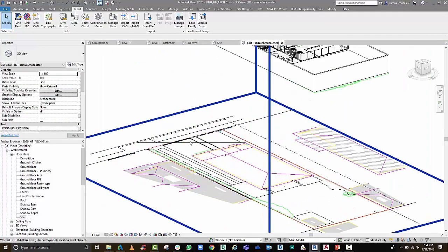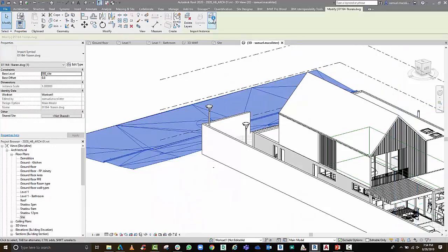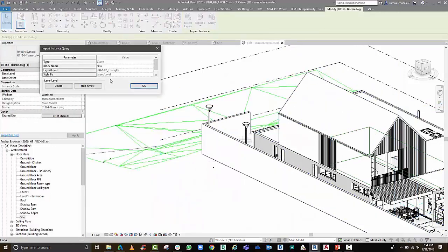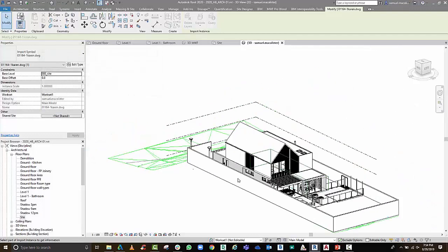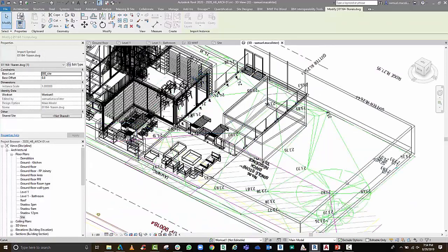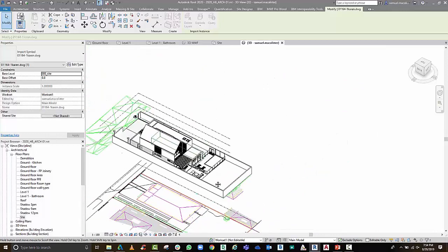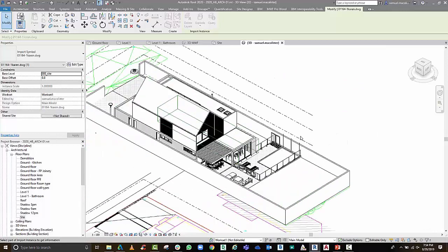You can see here in 3D as well, it's coming with information like topography information that's set up to the correct RL, the proper topography level. So if your surveyor is starting to work in 3D, you can bring that in and it will automatically come in with the right datum heights and also the spot heights that you're seeing here in the display. So it's another great way to reuse the CAD data to inform your Revit model, working with that topo information.